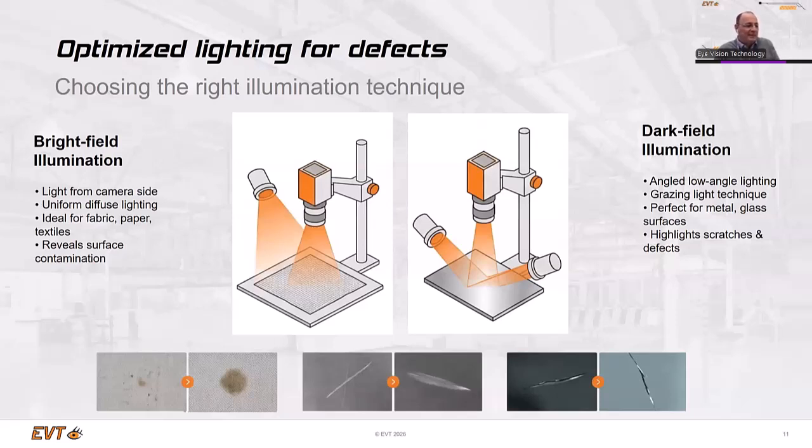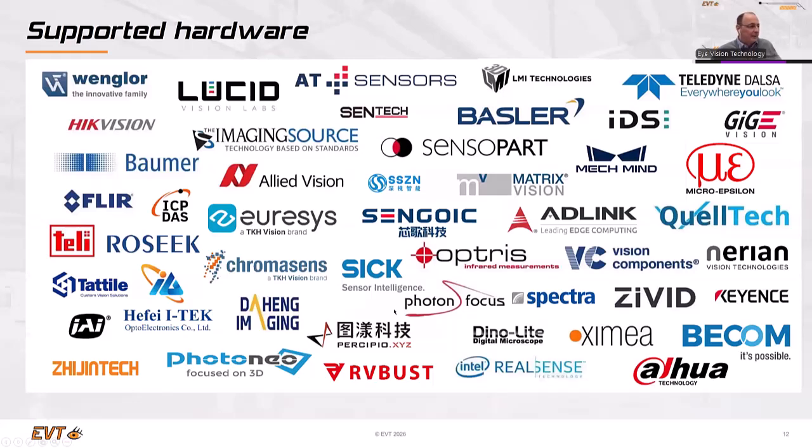Especially it depends on the angle to generate the contrast in this field of view, and to make this contrast in a very small area is much easier than to do it in any bigger area. That's one of the big advantages between an area scan and a line scan camera, based on the illumination side.